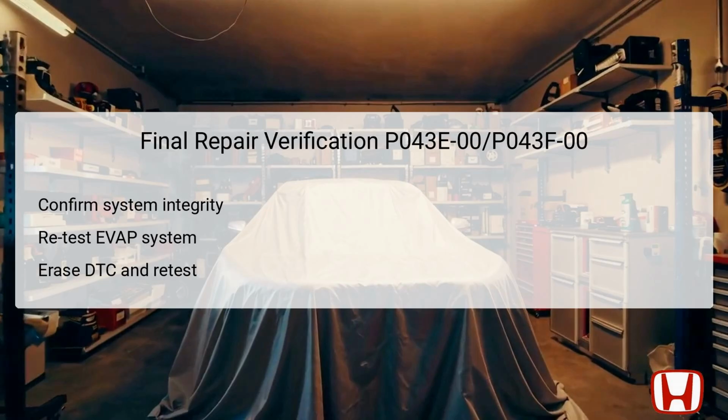Once repairs have been conducted based on your findings, it is essential to verify the integrity of the evap system before returning the vehicle to service. The verification process involves retesting the evap system using the HDS tools to ensure that the repairs have resolved the issue causing the initial DTC codes.